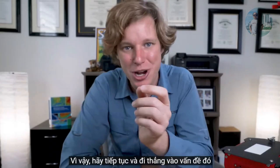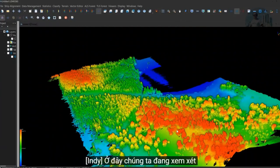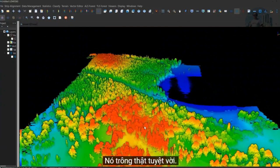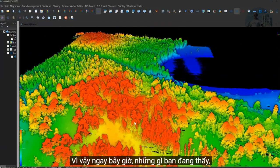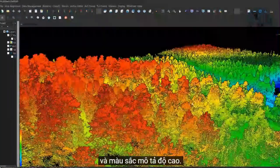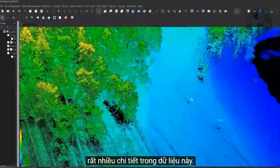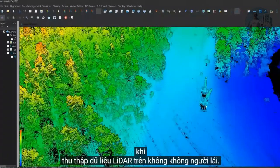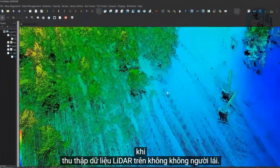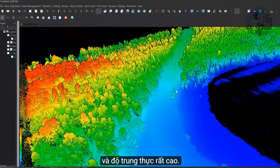So let's go ahead and just jump right into that and take a look at that raw point cloud data. Here we're having a look at that first LiDAR data. It looks awesome. So right now what you're seeing, if you don't know, this is the raw point cloud data. The red is high, the blue is low, and the color is depicting elevation. If we scroll around a little bit, you can see a lot of detail, a ton of detail in this data. This is what you're going to get with unmanned aerial LiDAR data collection. It's very high resolution, very high detail, and very high fidelity.